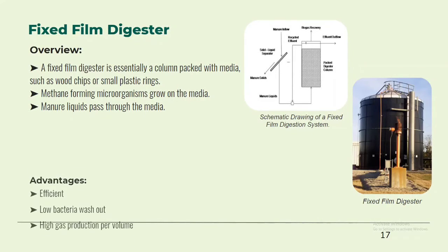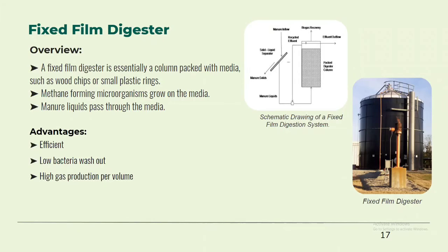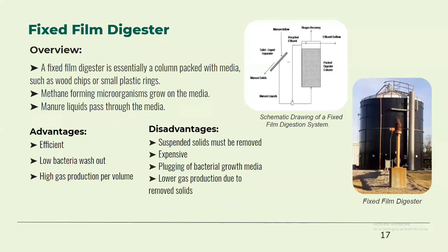Some of the advantages of these fixed film digesters are it is efficient, low bacteria washout, high gas production per volume. Some of the disadvantages are suspended solids must be removed, expensive, plugging of bacteria growth media, lower gas production due to removed solids.